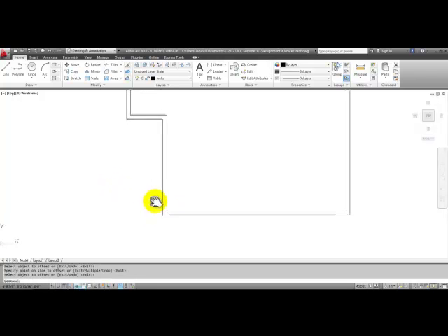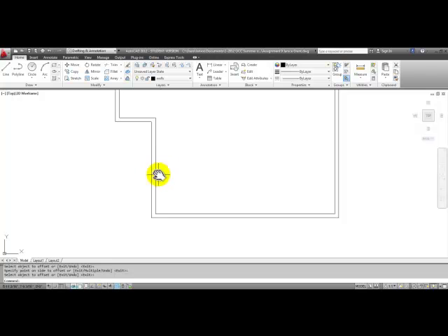Let's go ahead and explode these polylines so that they break up into individual pieces again. The explode tool is in the modify panel. It's underneath the erase icon here, and it's explode. Select both of these polylines and enter. Notice when you go close to those lines, now they're not all one piece and connected, but they've been exploded to individual lines. Now I'll start the offset command.